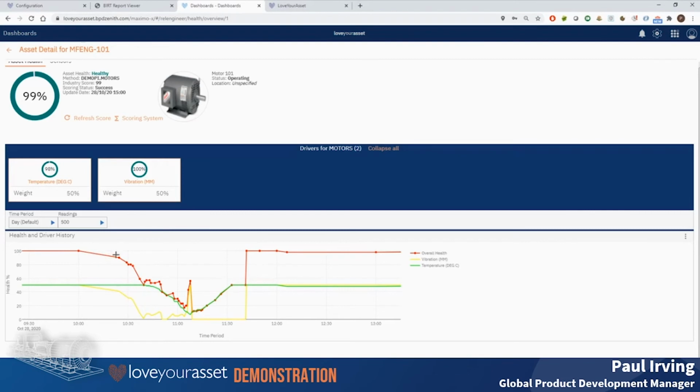So this is where we can choose to set our boundaries so that we know what's the best time to get alerted about it, give us enough time to actually go and correct things. Here we've got a spike of the vibration actually going back into its ideal temperature, right back up to 50. And the only reason that that's happened is because the vibration, as the machine stops, it's gone from the 25 back down to 1. And it's gone within its ideal range during that time.